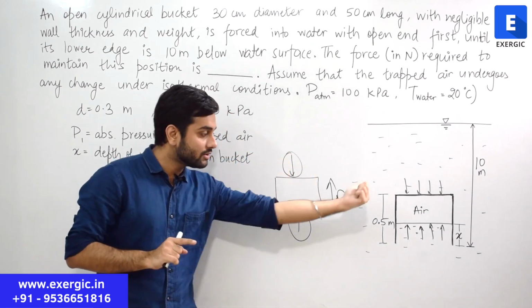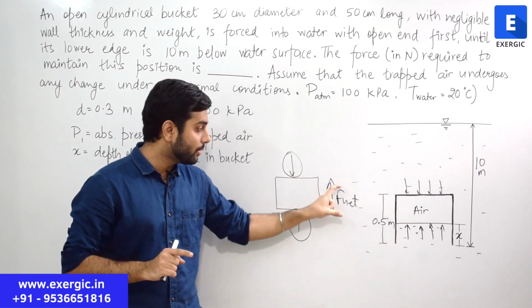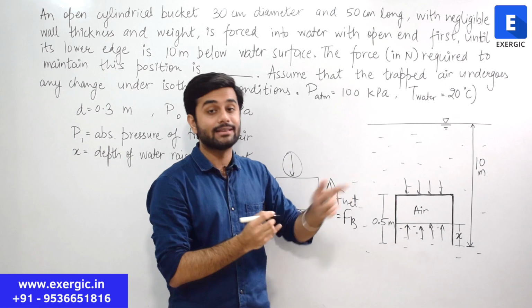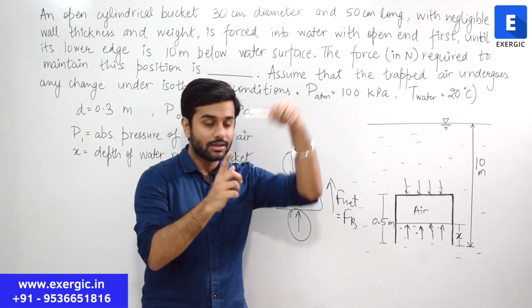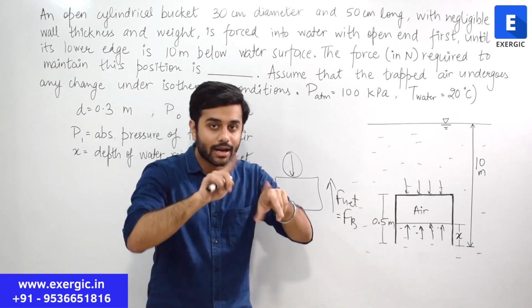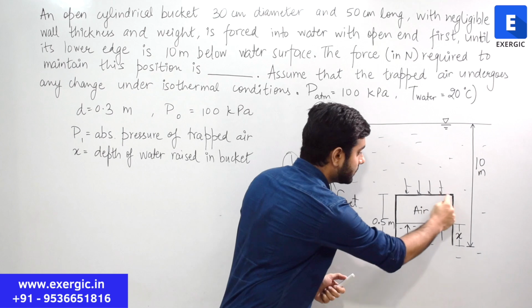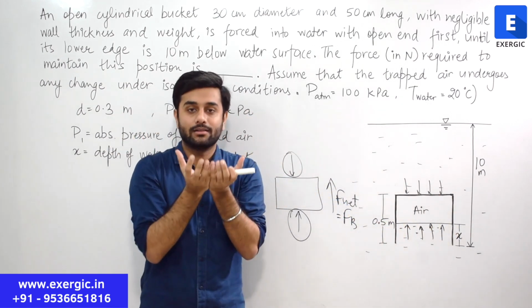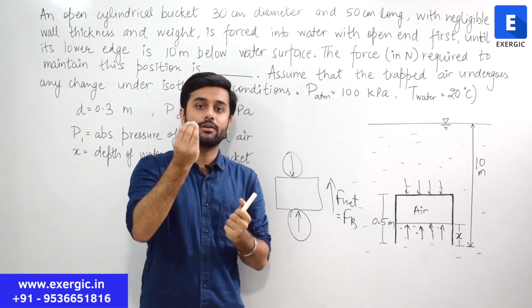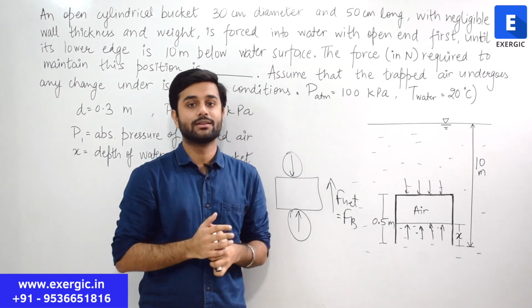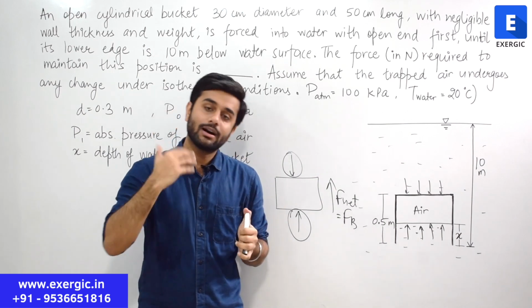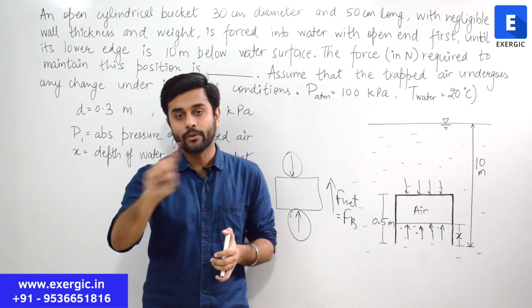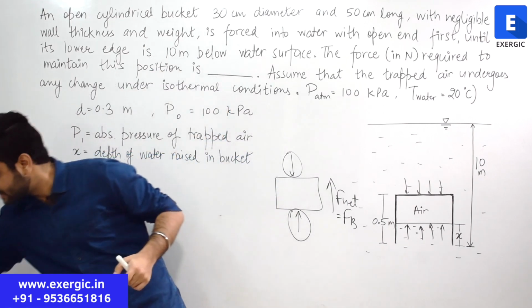The basic conceptual difference between the formula of buoyancy that we use, I have told you here. So you cannot apply this formula here, where I use the difference of these forces, or directly use the buoyancy acting on this volume. How much air has been displaced, that much volume, and how will the buoyancy force be equivalent to that much volume? I can find that out, and it will be equal to the net downward force required. No, it is an incorrect approach in this case.